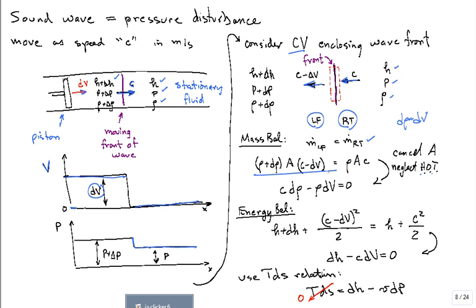All right. Energy balance. You do the same thing. You have the enthalpy and the kinetic energy, and then you can just do the algebra, neglecting the higher order terms, and you come up with this equation. You use basically an entropy balance as your third balance, but here we just express it as a T dS relationship about entropy, and then we say it's isentropic. So delta S is 0, so I have another relationship.